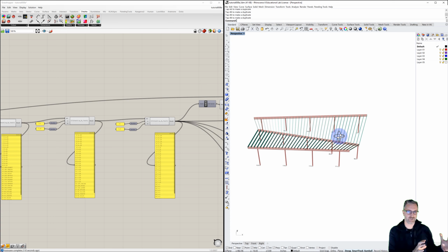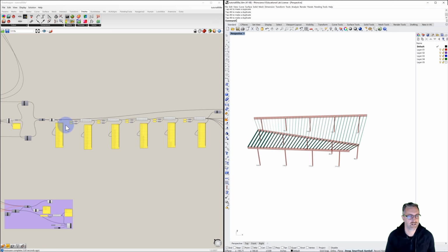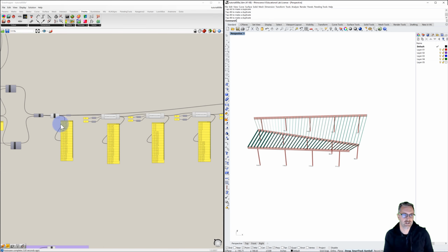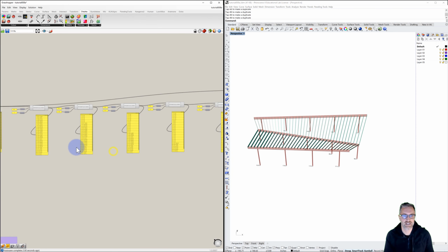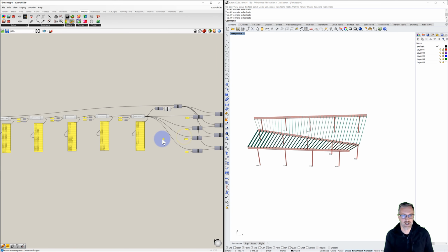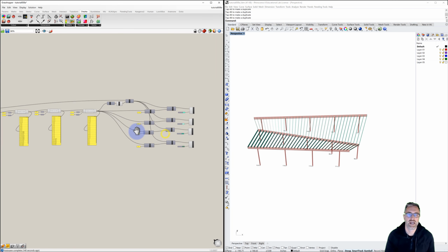So pretty big. We covered a lot in the first portion of the tutorial in terms of setting the columns and the girders. In the second part, what we've done is we've introduced the if statement and a way to, we're not really culling this list, but what we're doing is iteratively transforming the list from the lengths into their depth. And so there was a kind of rationale for that transformation. And then what we've also set up is color coding the different depths, because again, this isn't a gradient, it's a step function of the change in the depth of those rafters.